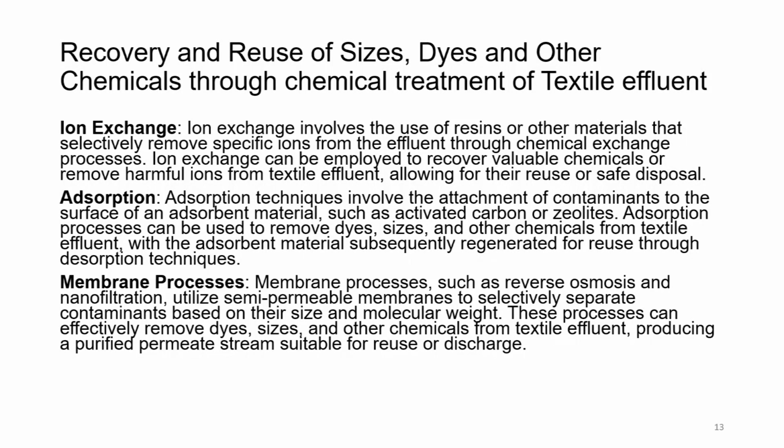Adsorption. The adsorption technique, where zeolite or activated carbon is used, involves the attachment of contaminants to the surface of the adsorbent material, and this we have learned time and again, such as activated carbon and zeolites. Adsorption processes can be used to remove dyes, sizes and other chemicals from textile effluent, with the adsorbent material subsequently regenerated for reuse through desorption techniques.